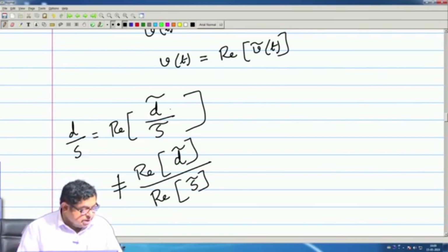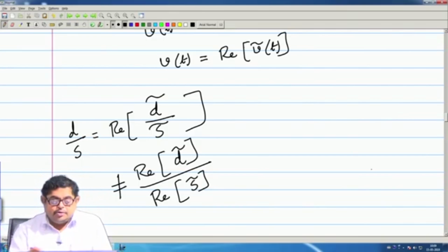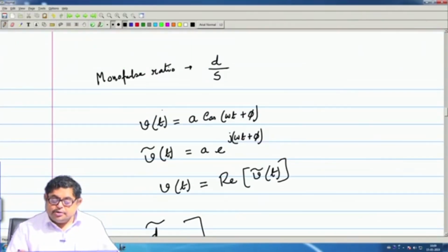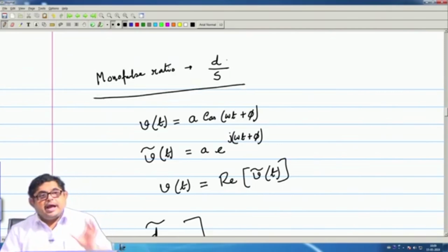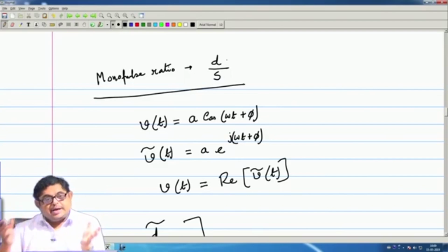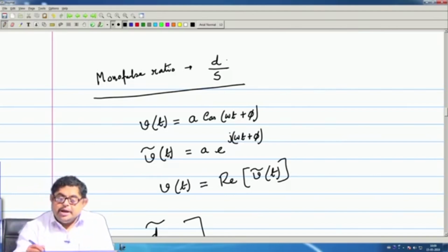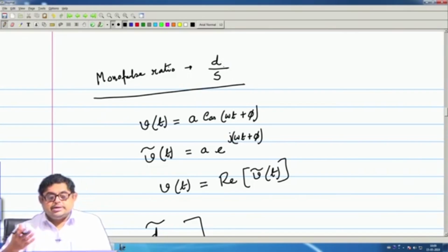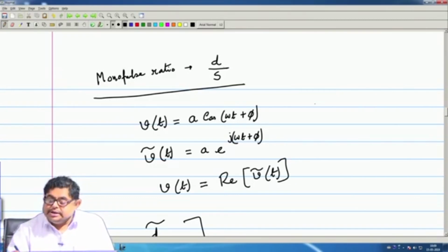Here also there is a caution. At RF level we form the RF monopulse ratio. The voltages are RF voltages, band pass signals, so for analysis we represent them by complex envelopes and treat the ratio as a complex quantity, and the actual thing is the real part of this quantity.